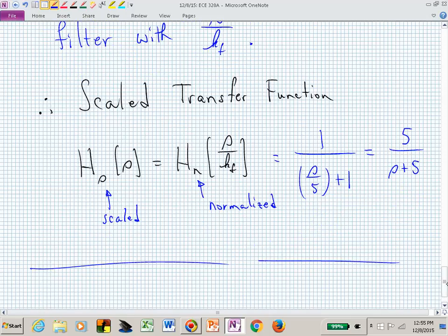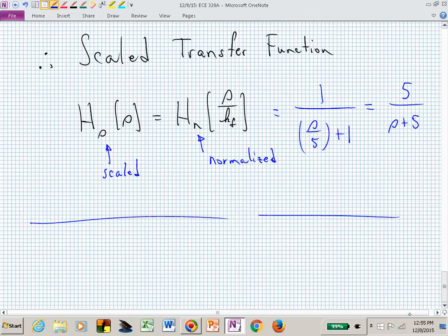If you needed a low-pass filter with a different frequency, you now know how to change the transfer function to achieve the frequency that you want. And the frequency is the location of the pole. And with our Butterworth, it's going to be the distance those poles are from the origin. In our normalized Butterworth, they will all be a radial distance of 1 into the left half s-plane.